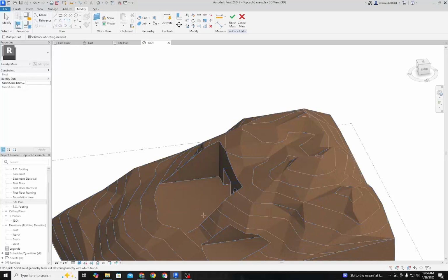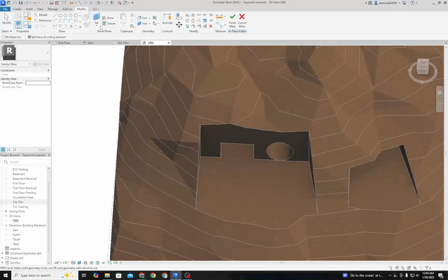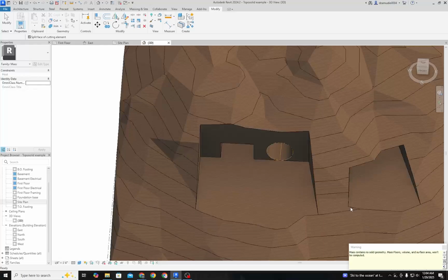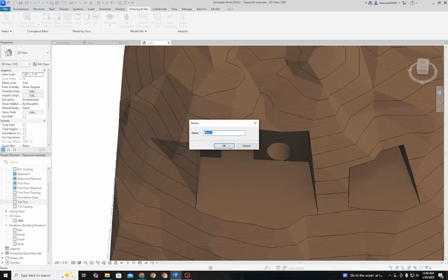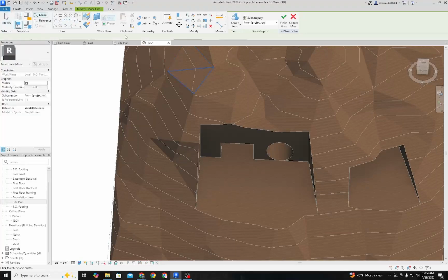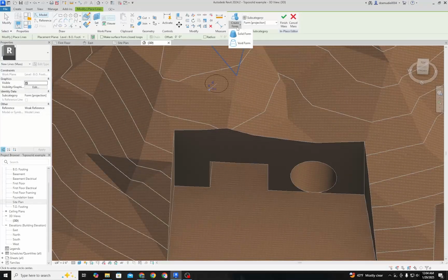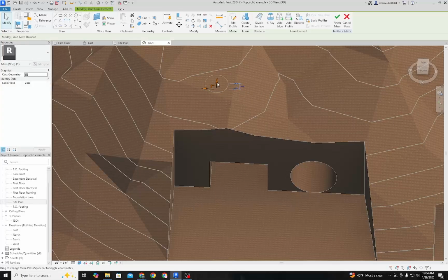And then we can also do that straight onto the toposolid. So if we wanted to create an opening straight on whatever the contour of the toposolid is, it treats each of those toposolid faces as a face. And so we can actually use that same face to create another opening following that angle of that face. So we'll see that here we're just creating a shaft that goes straight down, and it'll intersect our other existing tunnel.